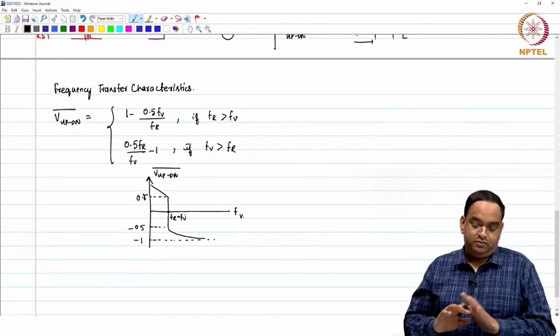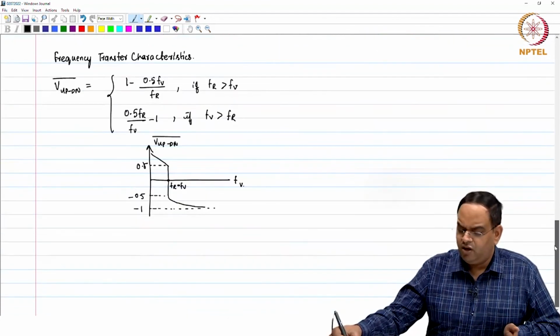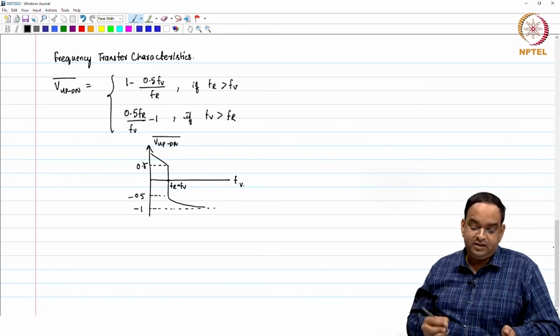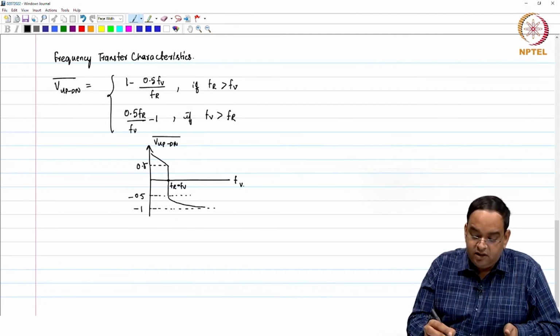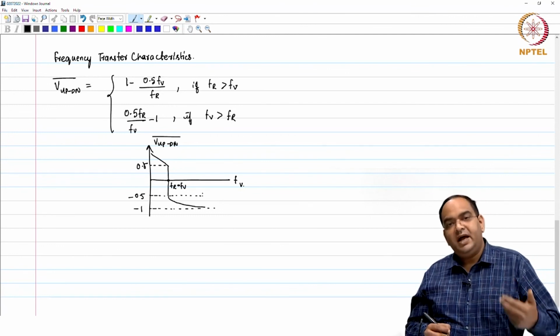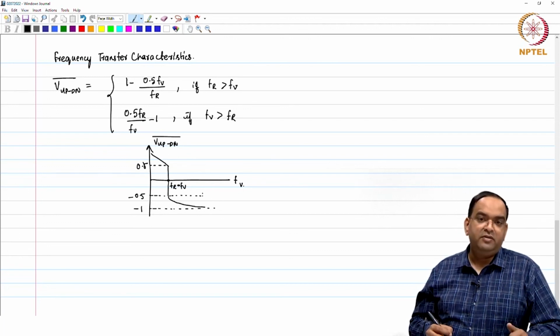So, well, this transfer characteristic you may not use in your PLL. The only thing it is telling you is that if I use this PFD, I will detect the sign of the frequency error correctly. I will apply the correct change to the VCO's frequency all the time, and I will acquire the frequency locking also.